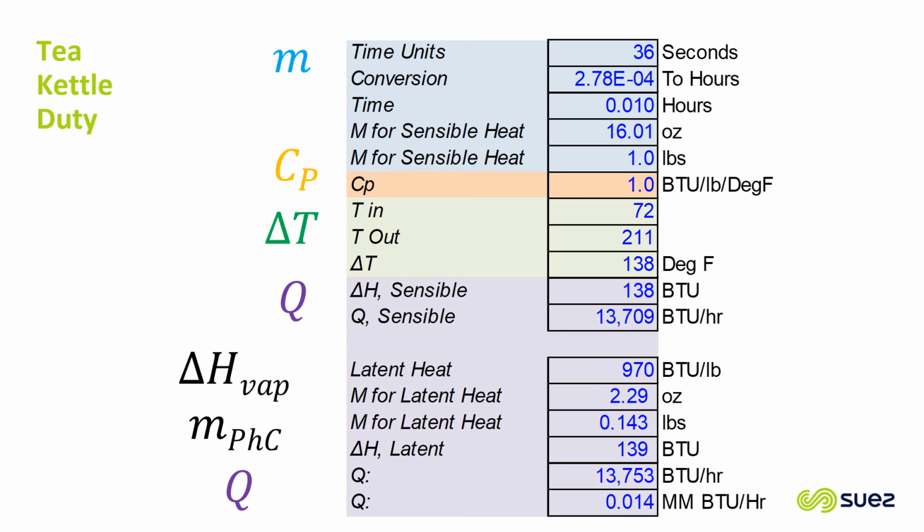Okay, we want to realize that this is a semi-batch operation, and everything in a refinery is on a continuous basis. Another big difference here is this is a pure substance. Boilers have pure substances in refineries, but most of the time in a refinery, things are a complex mixture. So what we have to do to get these numbers to a rate is to get them per hour, which is the way we do duty calculations anyway.